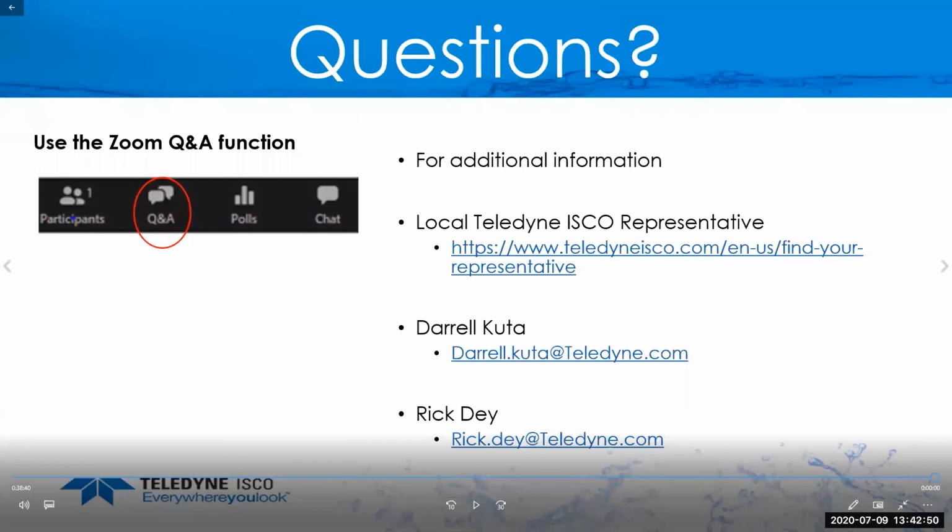So as far as the ISCO laser flow sensor, we can go all the way down to 1/2 inch of water depth, and the minimum velocity is 0.5 foot per second. Now with other technologies, their range is the minimum level. Yeah, it's anywhere around an inch or so, but you need to look a little closer at the velocity. We need to make sure that there's enough surface turbulence to get a return signal with a radar sensor.